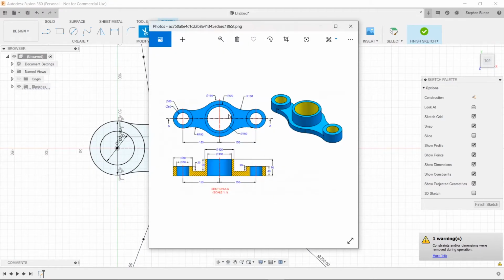That looks really similar. And so now it comes to the point of actually extruding it all. And that's pretty much it. It's pretty simple. So what we need to do is, if you see here, it doesn't give a depth here, but it does say that this height is 20 from this face, and the overall height is 40, so 40 minus 20 is 20. So we know that the height of this base here, at least this portion, is 20 millimeters tall. So let's do that.